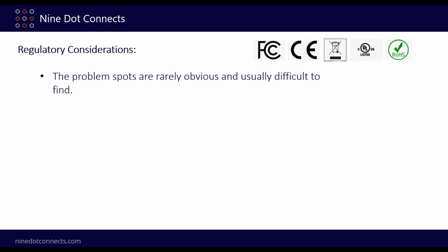And I can tell you right now, if you have the opportunity to just hire a consultant or things like that, it's so well worth it if you're not sure about your regulatory or your design and how it's going to pass. Because remember, regulatory issues always come up at the end of the program. Usually, you built a board, you've got it working. One of the last things we do is try and get through regulatory or compliance, and it fails, and now you could spend weeks or even months working on that. Whereas hiring a consultant or something like that can save you enormous time and money.